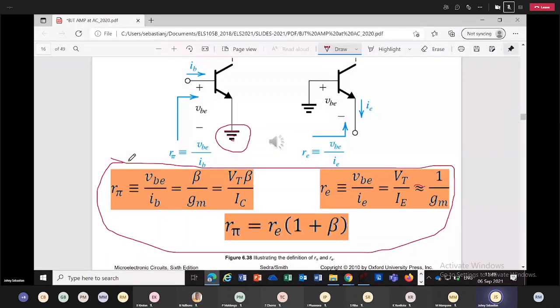And how do you work out VDC in a power supply? Vm minus V ripple peak to peak divided by 2. That you need to remember from the slide. What you need to remember in the power supply chapter: V ripple peak to peak equals IL divided by 2FC. That you need to remember. So that's the only formula that you need to remember in the power supply chapter.